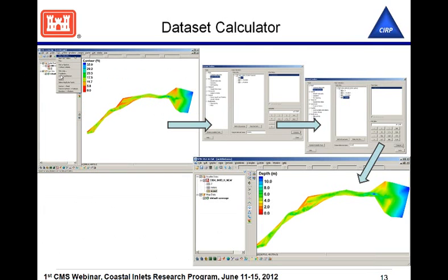So you would go into the data set calculator. It's under the Data pull-down menu, you hit Data Calculator. It brings up a toolbox that's shown here. It's hard to see, but I'll show in a minute. There's a data calculator, and it lists all the various items that are in your scalar tree. So there may be other things that are listed, but we're only looking at what's in the scalar data set right now. And right now there's only a Z, but it also adds in an X and a Y as well in case you need to use those for any kind of computations.